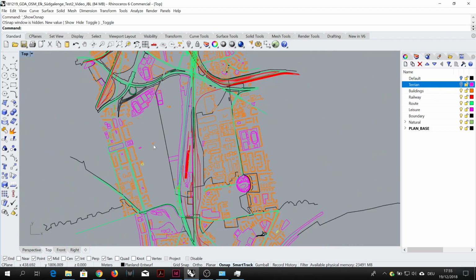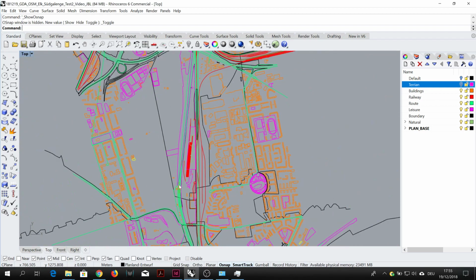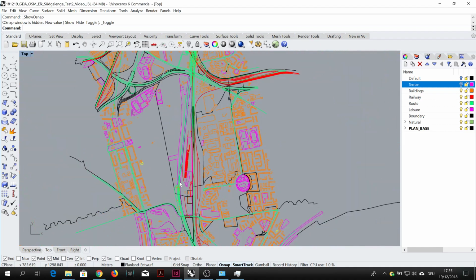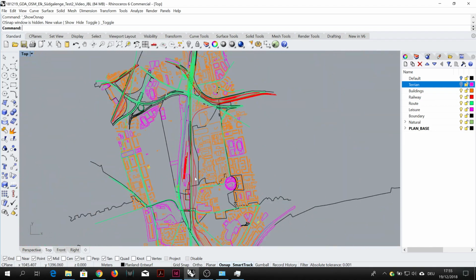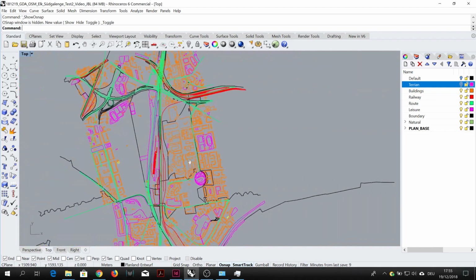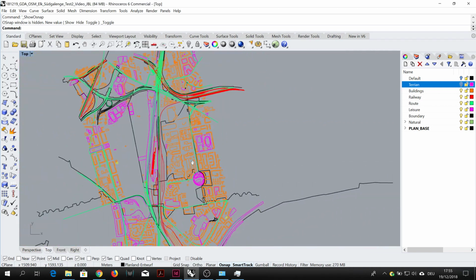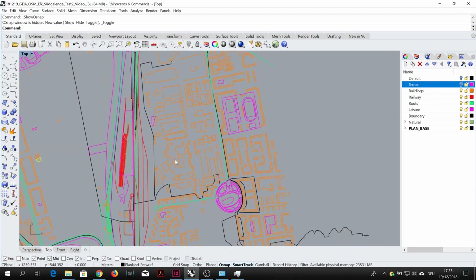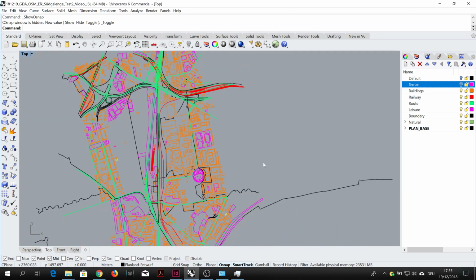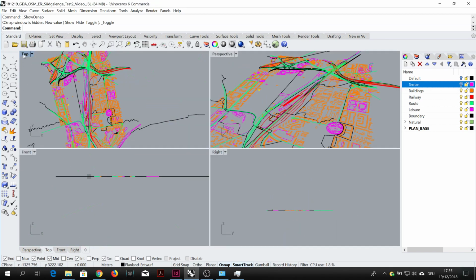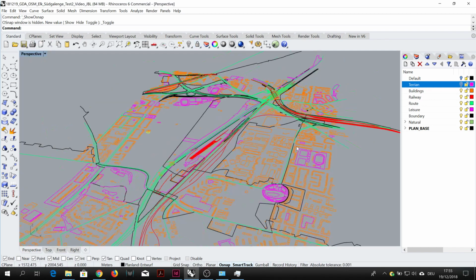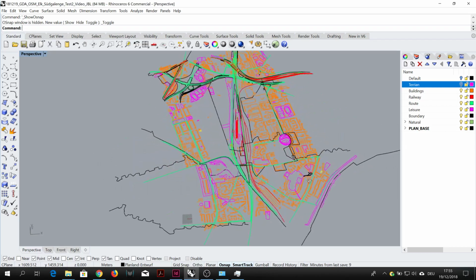To navigate through in Rhino, if you haven't already used it before, to zoom is just the scroll middle mouse button. To pan left and right in top view plan is right click and move. To get out of the top view into your four views, you double click the view and then double click again onto a different view, and then you're into a different view space.